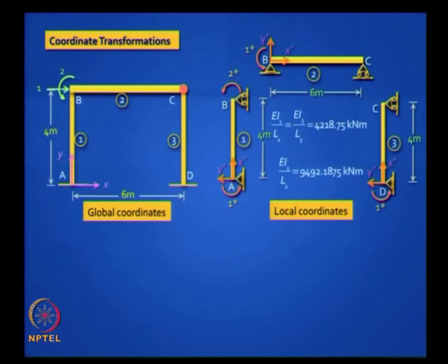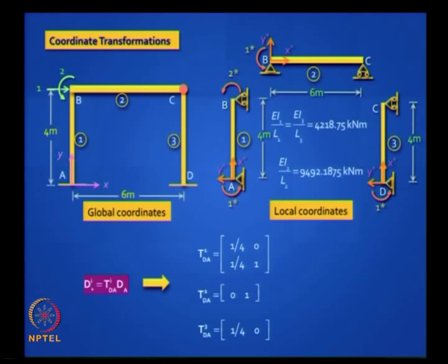You have 2 degrees of freedom for element 1, no change there, and you have only 1 degree of freedom for elements 2 and 3, and you should release at the right place where there is the moment release, there is the hinge, internal hinge at C. It matters little whether the hinge is internal or at a support. Clear? Okay. How will this change? This is the change. Okay.